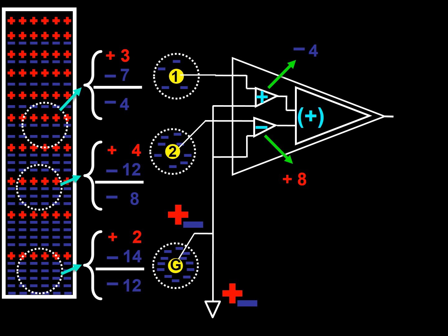At this point, these values are presented to the driver amplifier, and the common mode rejection ratio of the amplifier will further modify these values. In this case, and for the sake of clarity, the common mode rejection ratio in this illustration is 100%, thus implying that in this fictitious differential amplifier, all that is equal will be rejected.